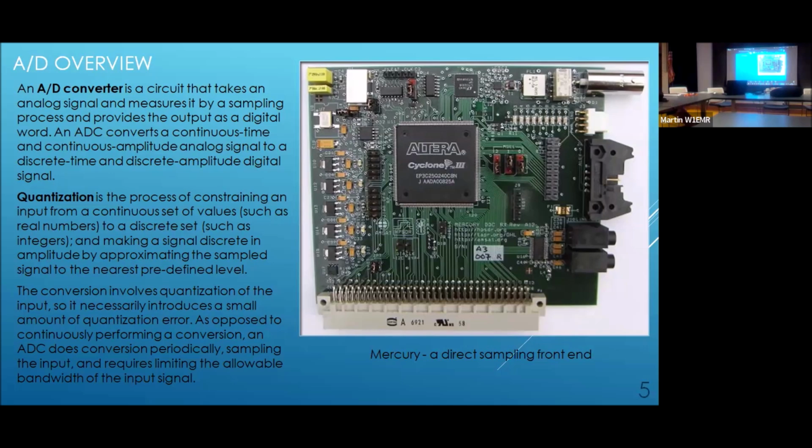So thank you. Okay. Yeah, the quantization involves putting the input into a stair step. So if the step size is small, it sort of doesn't matter. But if the step size is very large, i.e., you run out of bits, or you're really using a very cheap A to D, take your pick, it may have an error that'll affect the quality of the signal or the quality of the sound. And that's something we have to pay attention to. You've got to make sure that it's going to be accurate enough to do the job that it has to do. Okay, so that's important.